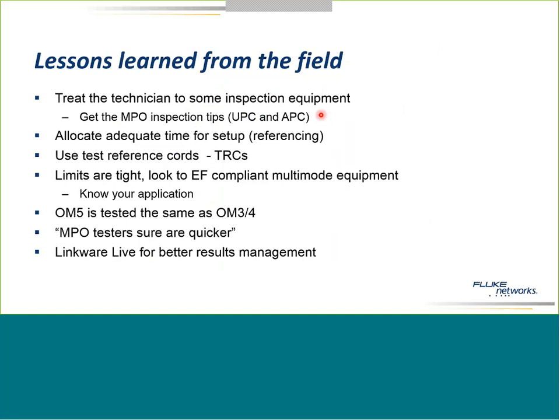And it's just such a state of confusion. Is the cord dirty? Is something going wrong with the tester? No, you really want to make sure that you have inspection equipment, and if you're doing multi-mode, you'll need the UPC tips, and if you're doing single mode, you're going to need a second tip.